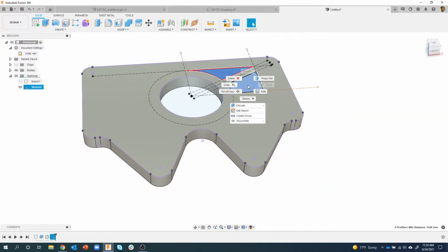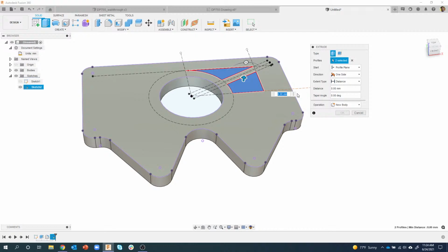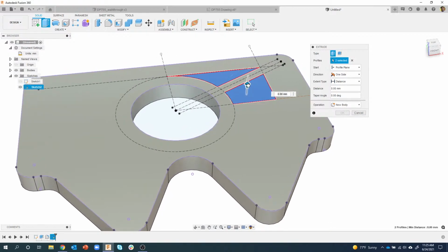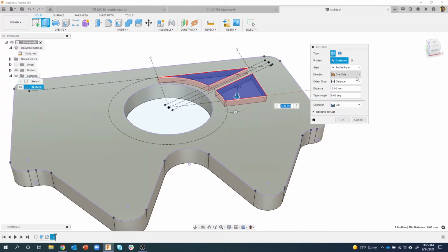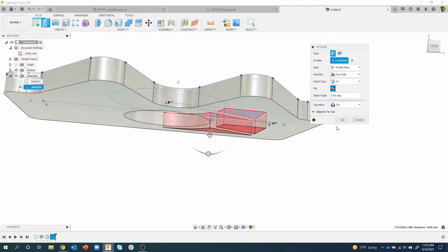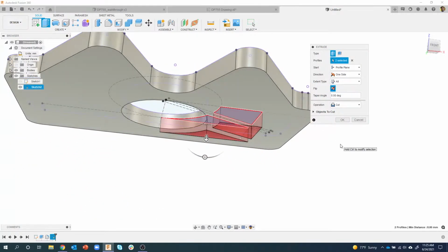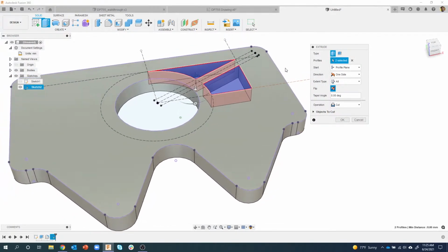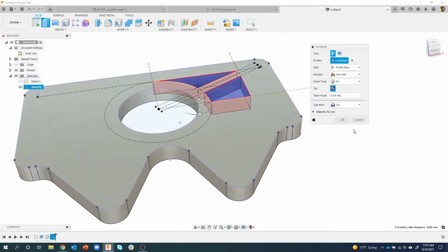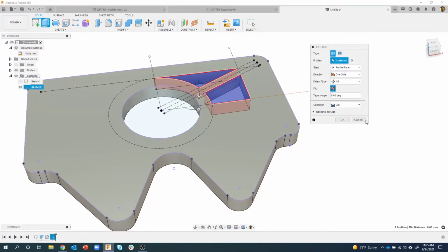I'll go ahead and extrude these guys. I'm going to start to push down so you can kind of see what's going to happen. Instead of typing a distance, I'm going to say go through all. That way I don't have to remember, was it 12, was it 24, was it 13? I don't care. I just want it to go all the way through the object, like so.